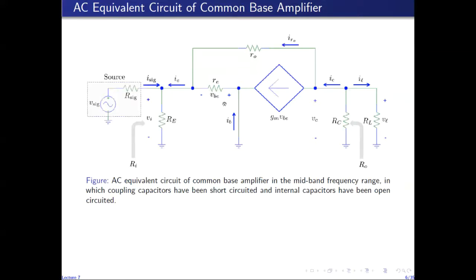The base is directly short-circuited. This is the small signal resistance in the emitter branch, the emitter resistance RE, because this is the emitter terminal, and this is the source which is connected to the emitter terminal. This portion here is the augmented small signal T model of the device. I have chosen to use the T model because it makes the analysis rather convenient.